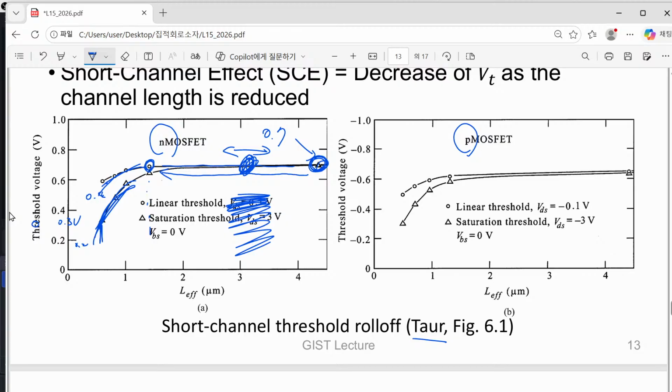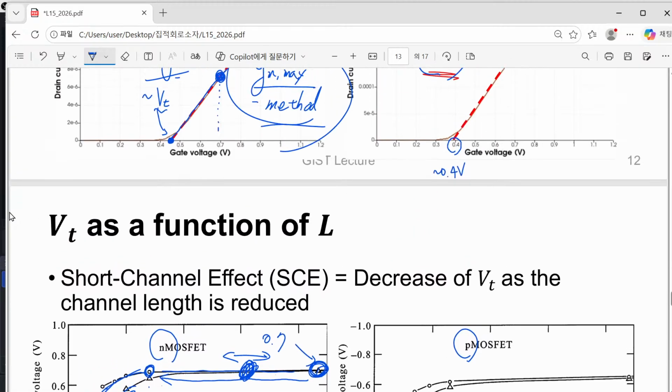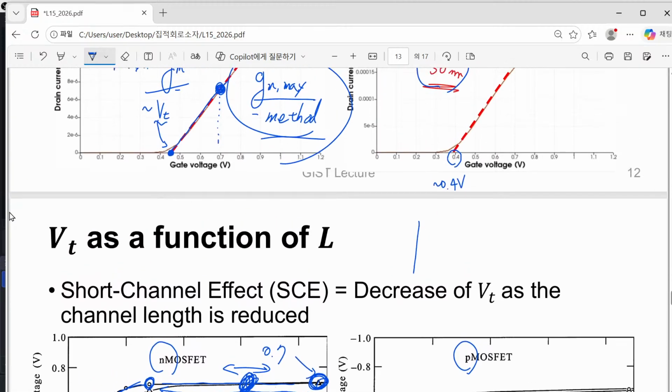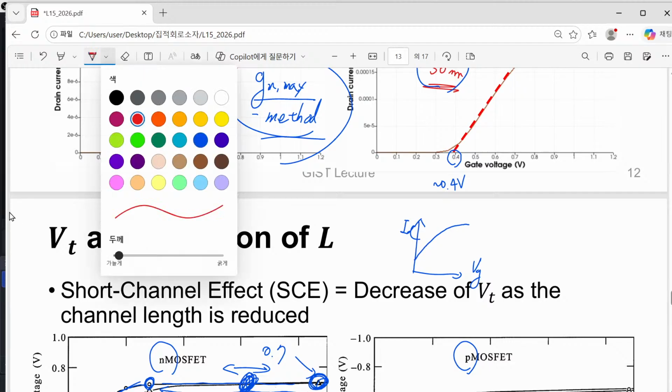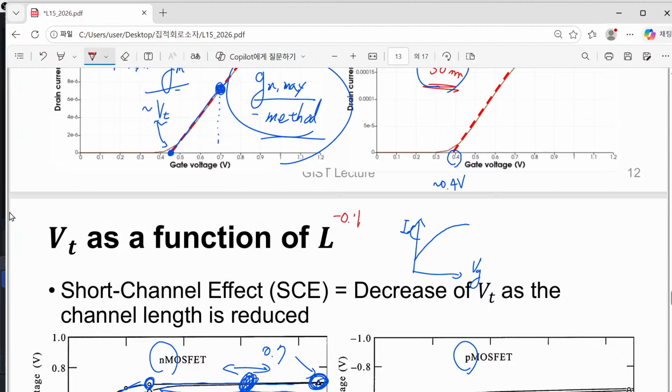In our case, yes, that is a really big problem, because when you introduce your threshold voltage shift, then what you will have is, when you draw your ID versus VGS, and now let's say that this is the one you wanted to have, and let's say that you have minus 0.1 volt shift of your threshold voltage.